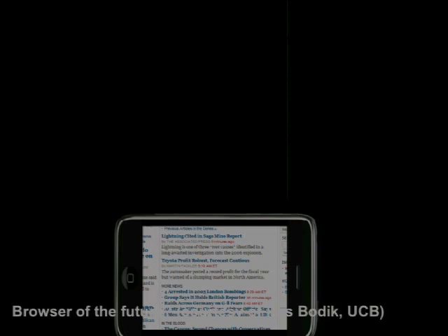The accelerometer measures acceleration, and what we really want is position, not acceleration. Position is a double integral of acceleration, and you're going to get accumulating errors, right? So presumably, if you have a small error in the measurement of the acceleration, this thing will drift.